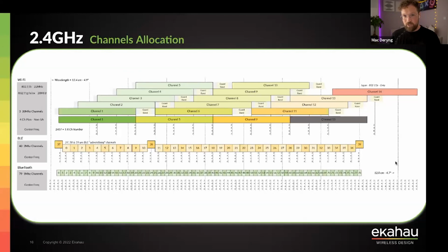So on 2.4, we not only don't have enough spectrum for modern applications like voice and video, we also have tons of other wireless, not necessarily Wi-Fi, devices working in that band. We have Bluetooth, BLE, Thread, Zigbee, all the IoT stuff. We have analog cameras, analog phones, you name it. And it all might work on 2.4. If you have those devices, they will use quite a lot of airtime, and therefore your Wi-Fi devices will defer and will not have the opportunity to use the spectrum. So that's 2.4. We call it a legacy IoT band these days.